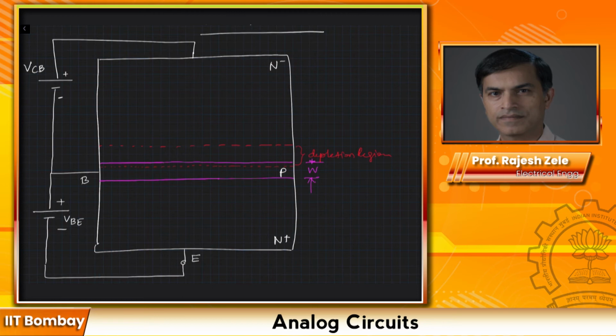I'm also going to show you the width of the base region. Earlier, if you remember, when we just had the base-emitter junction, we had this nice exponential decay of the carriers. And we said that the current of the electrons is going to flow this way. However, as soon as we brought in the reverse-biased p-n junction, the carrier concentration goes to 0 at that interface, and this yellow curve will morph into something like this.